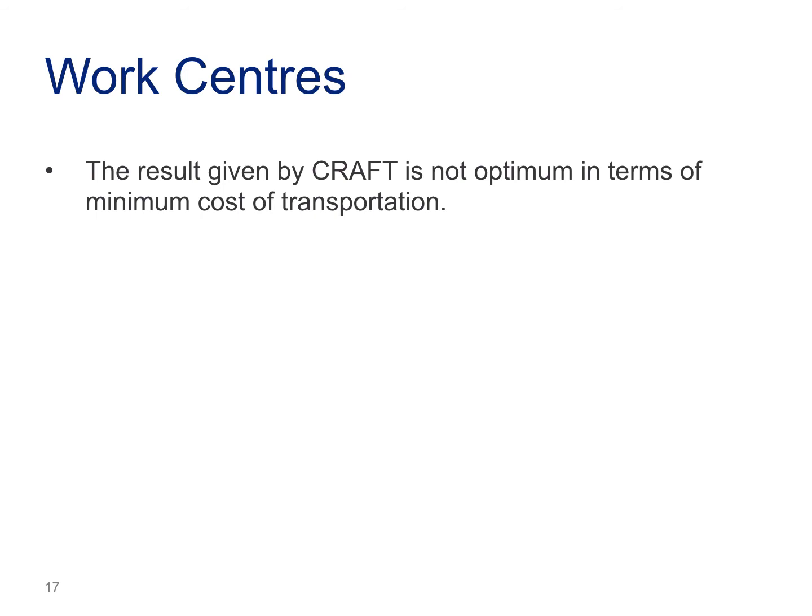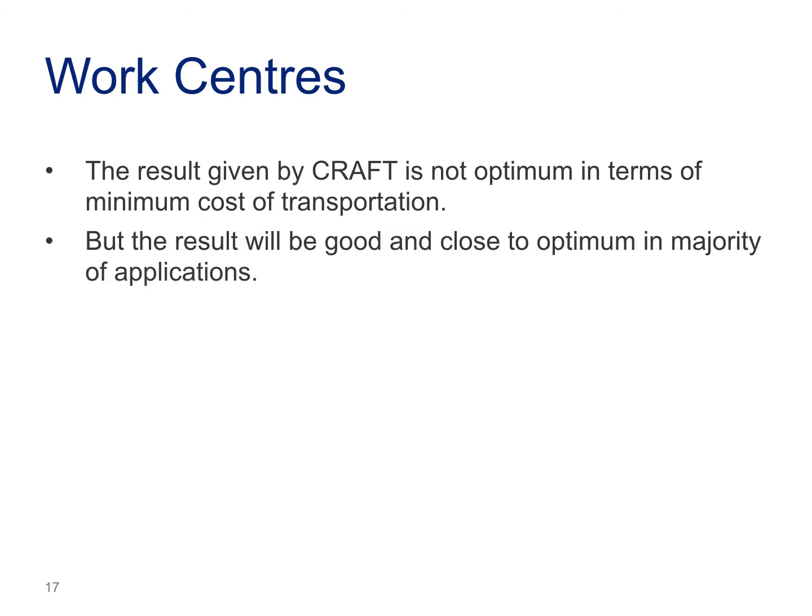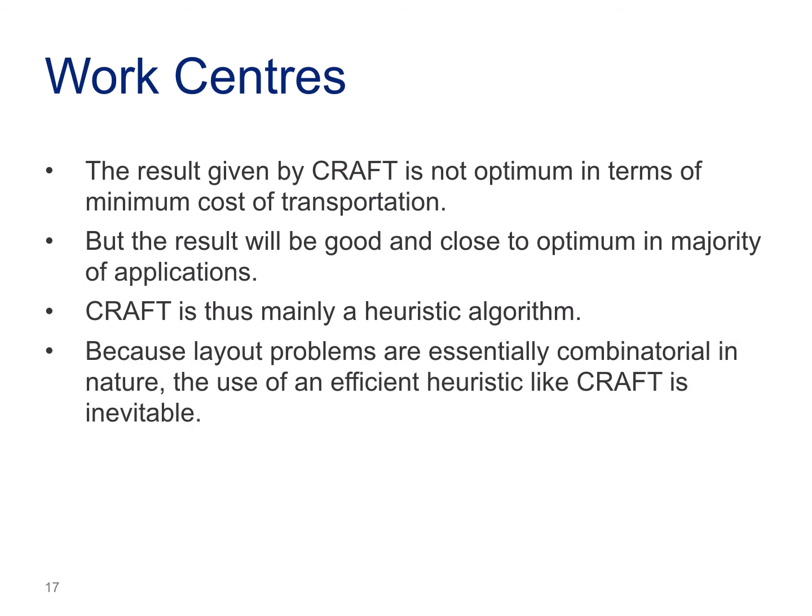The result given by CRAFT is not optimum in terms of minimum cost of transportation. But the result will be good and close to optimum in the majority of applications. CRAFT is thus mainly a heuristic algorithm. Because layout problems are essentially combinatorial in nature, the use of an efficient heuristic like CRAFT is inevitable.